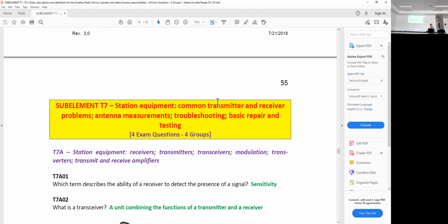Shielded wire, is that like a cable for my cable TV and stuff like that? Yeah. Mm-hmm. In that case, it's working a little bit differently. You're sending your energy down the center, and you're using the shield both to block external signals as well as keep your signal on that center. So usually when they talk about a shielded wire, there'd be multiple wires with one shield around them. So it's a little bit different than a coax, but similar.